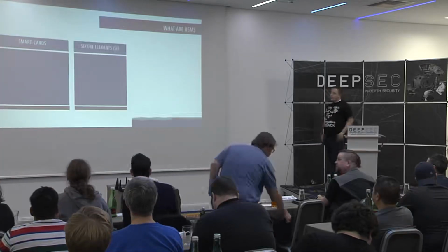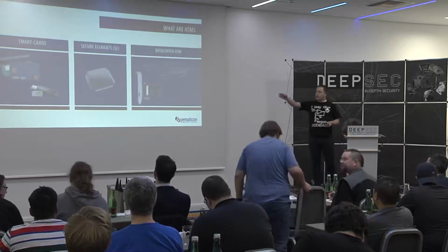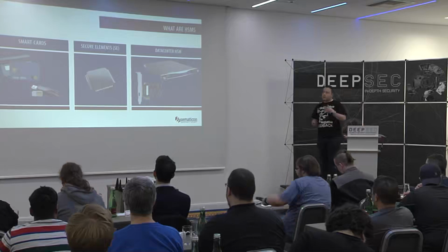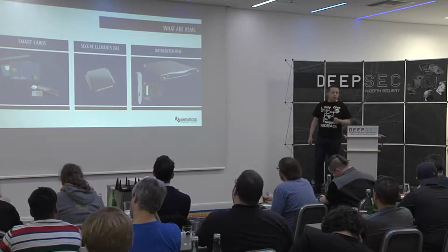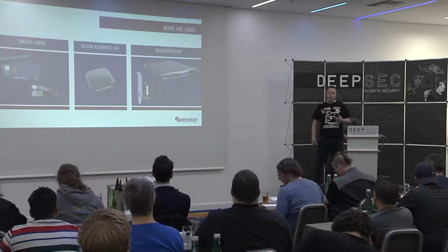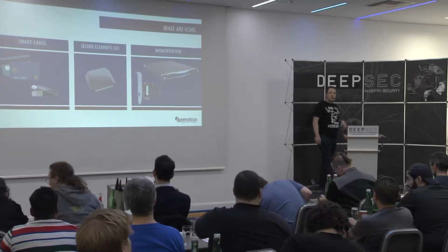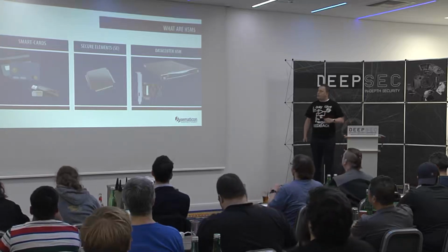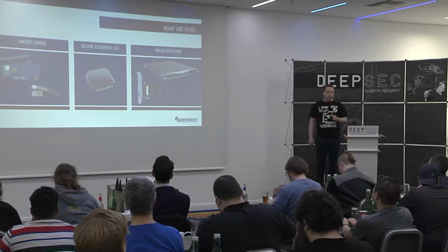So what are HSMs? All of us have HSMs in the pocket. We have different types of HSM. We all know, let's say, the smart cards. Each smart card we have, each credit card, is an HSM. The HSM itself protects the key inside, generates the key inside, and the key can never leave the box. Especially for digital passports, you may have the Austrian Bürgerkarte, for example, or something like this. The key is generated inside the card and can never leave the card. We have secure elements like TPMs, which we know from our computing environments, or which should be in embedded devices, and we have the data center HSM. Because the world runs on crypto, all our banking account stuff is protected by HSMs, which are made for the data center stuff.